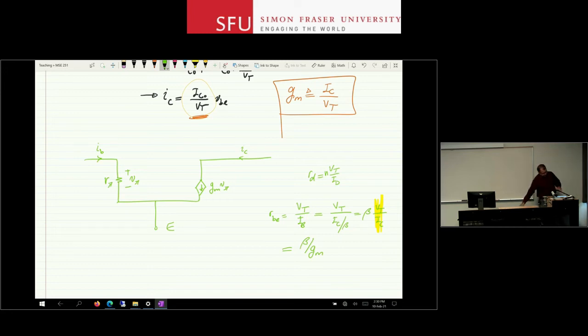Now, we started with an NPN transistor, which has a large signal model like this, and got to this small signal equivalent, right? So this is NPN. So this is VBE, and this is IS e to the VBE over VT.